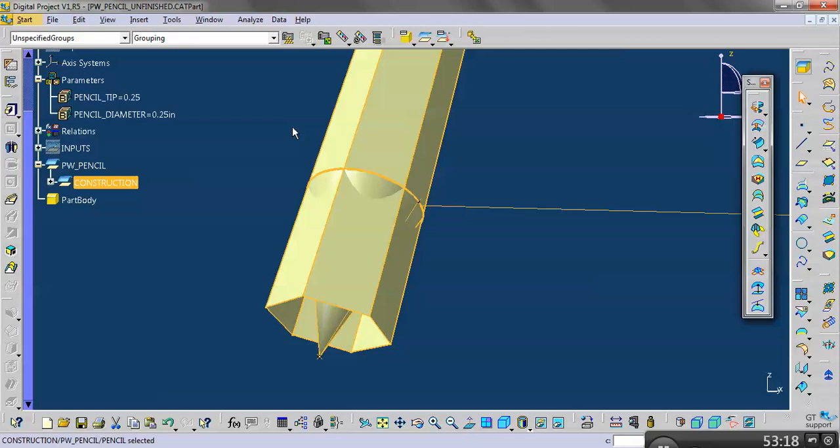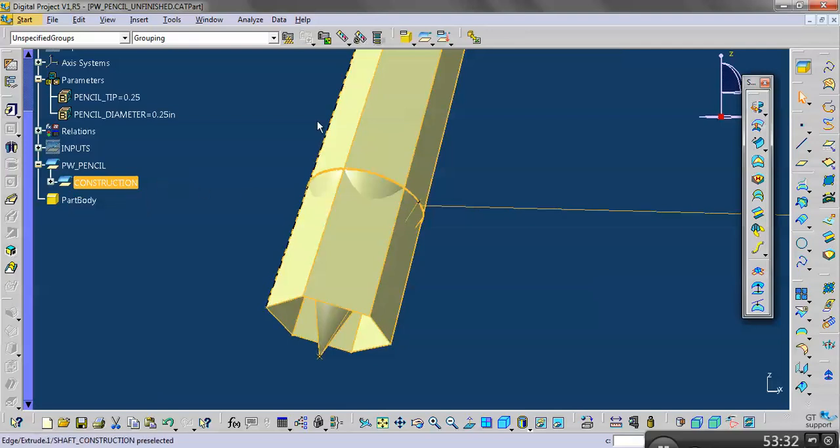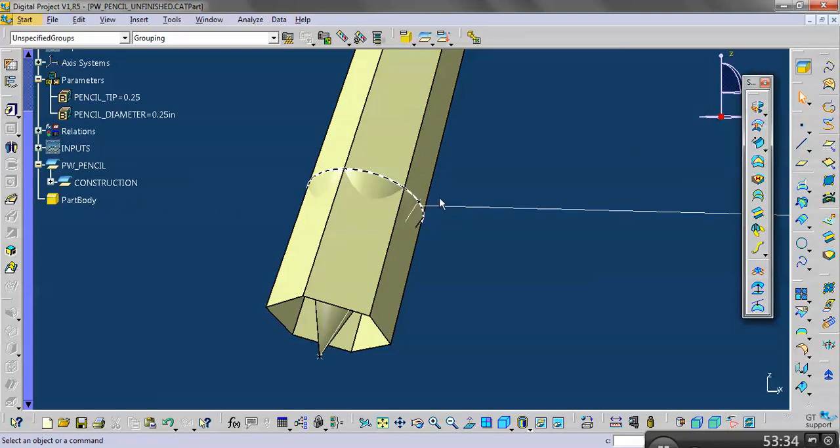I'm going to make a surfaces geometric set. I like to separate construction from final surfaces because it's easy to hide construction and leave just the final surfaces visible. That's why I pulled out the control geometry also, so I could hide all the construction, leave the control geometry visible and the construction geometry visible in the finished file.